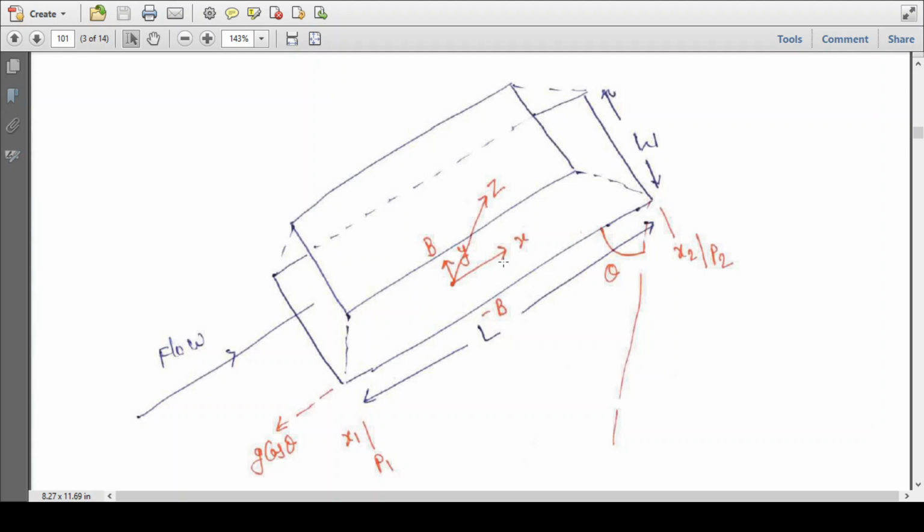The direction of the flow is considered as x and the variation in velocity is considered only in the y direction, which is the direction of the gap between the plates. Because the width of the plate is significantly large as compared to the gap between the two plates, the maximum variation would be only in the y direction as compared to the direction z. There would be no variation in the x direction because we have considered fully developed flow.